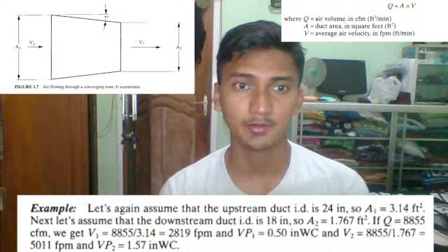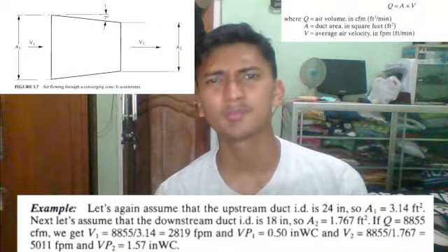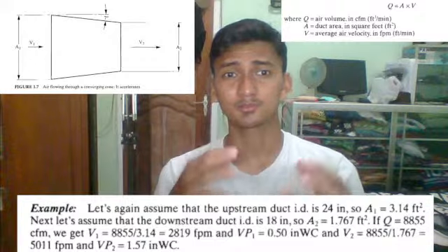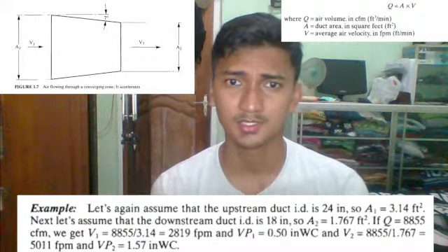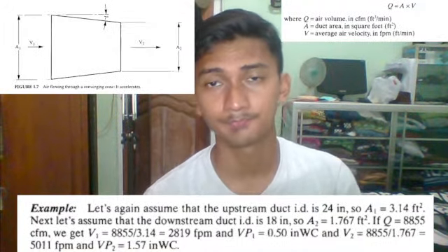If a little air spin remains past the fan, it is multiplied manifold as air travels to a smaller diameter, because it tends to retain its circumferential component.